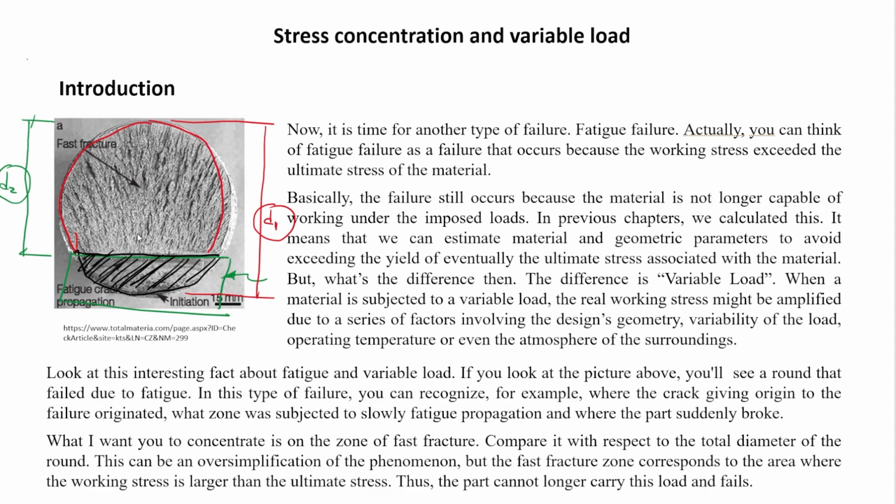It depends on what type of procedure we use, what type of standards were used, for example, when manufacturing that type of material, which are things that we cannot control, but the manufacturer has to control at a certain point, but there are ranges. So there's a bunch of details when calculating, and that's why those values we are using as yield strength for the material can be even overestimated or underestimated. That's the difference related to that.